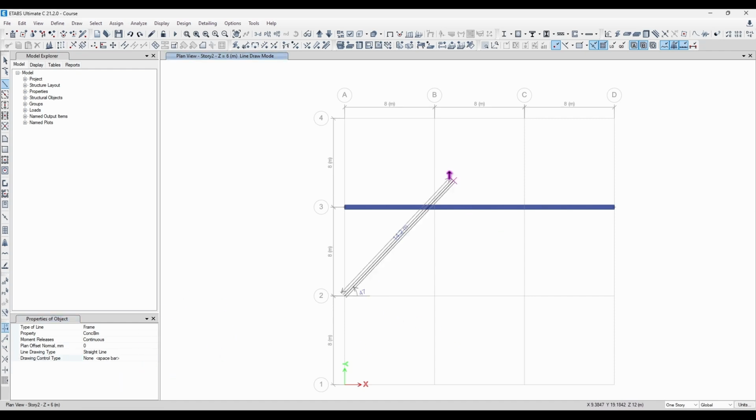You're technically just drawing the beam however you like it, which is the default setting. Another option is parallel to some sort of angle, so you're going to draw your beam without a specific length, but with a fixed angle. Then you can draw it parallel to the x-axis or parallel to the y-axis. Let's start with this one. It's going to draw the beam always vertically, and parallel to the x-axis, which is going to draw the beam always horizontally.